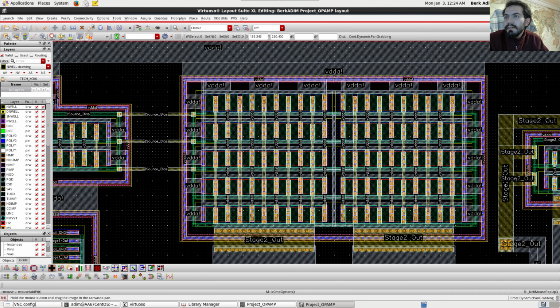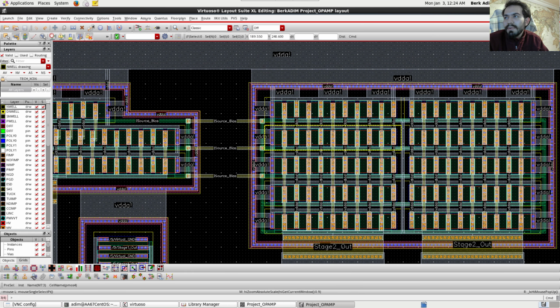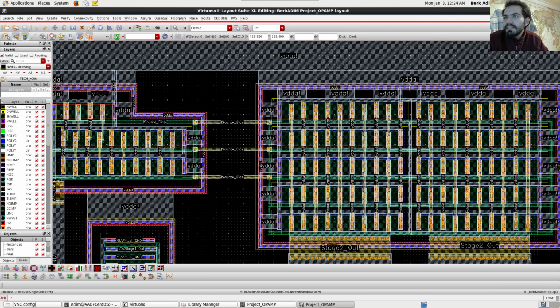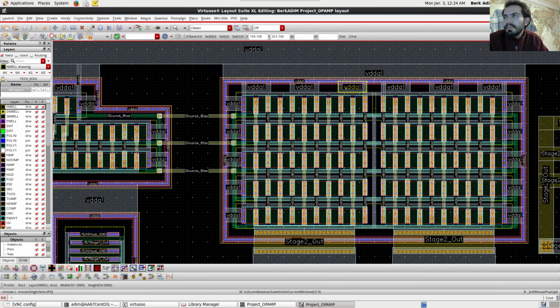And here, this transistor has twice the amount of width compared to this transistor. I am talking total width here. It has actually 6 of the same connections here compared to 5. So this is going to have half of the source resistance, which will mean it has the same source voltage.